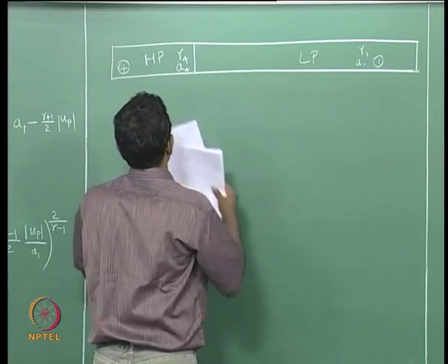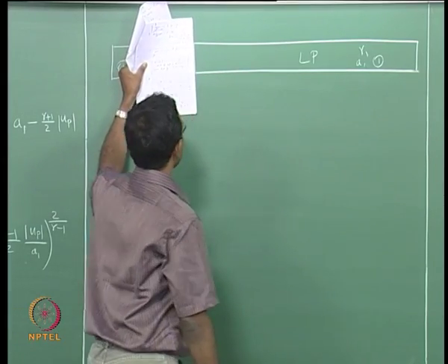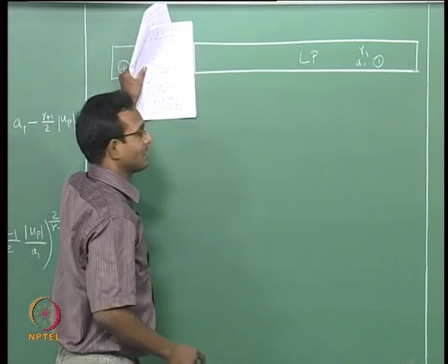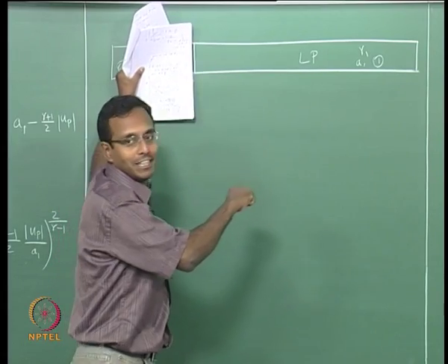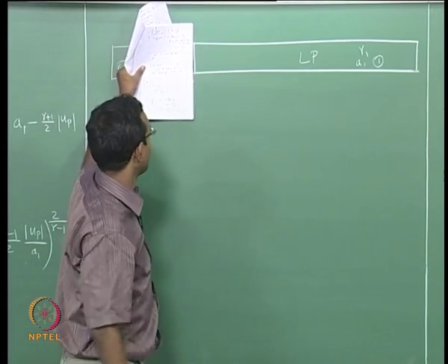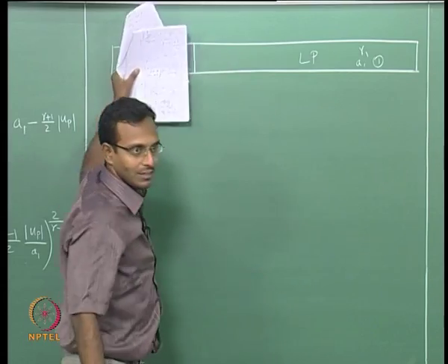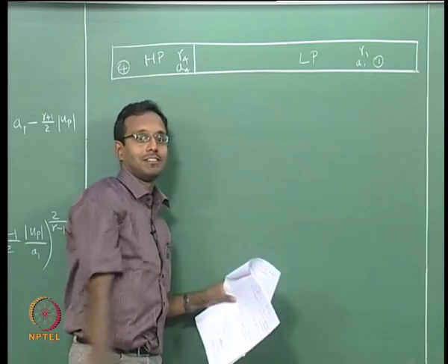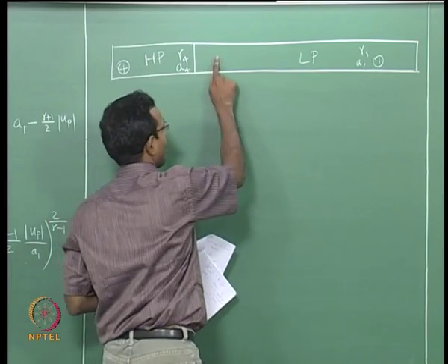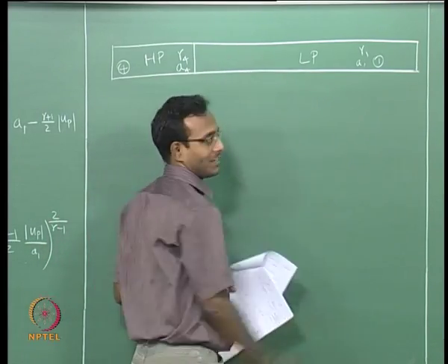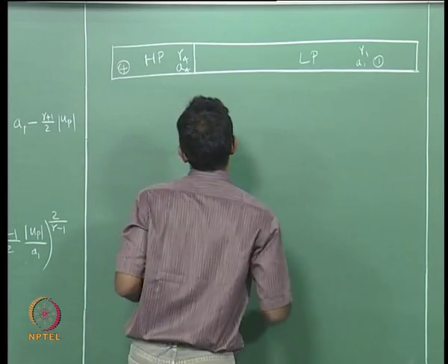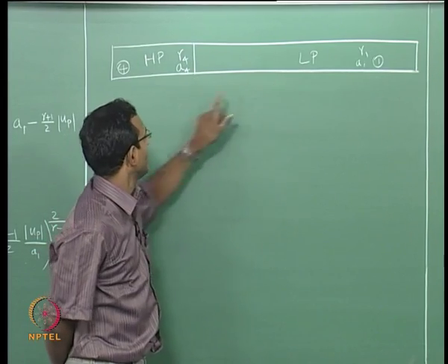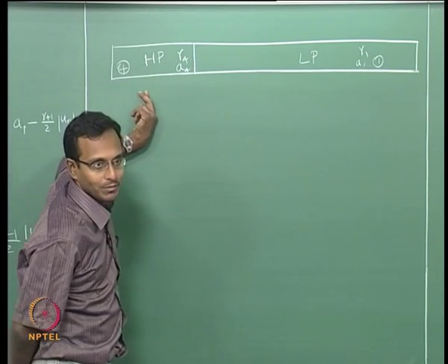Now I will look at it the other way. In here there is a huge high pressure gas sitting here, and suddenly it is going to be pushing at t equal to 0 onwards. Okay. If it is pushing against this low pressure gas, then I am going to have the other problem of a piston traveling against the flow, and thus going to develop a shock, and the flow is going to go behind it this way. Okay. So overall what is going to happen in here, I am going to have a shock traveling this way and a set of expansion waves traveling this way.